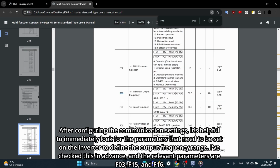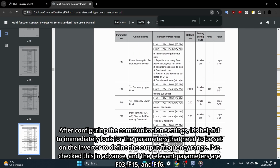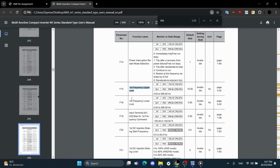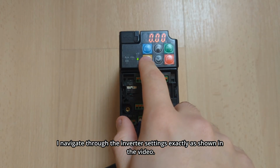After configuring the communication settings, it's helpful to immediately look for the parameters that need to be set on the inverter to define the output frequency range. I've checked this in advance, and the relevant parameters are F03, F15, and F16. I navigate through the inverter settings exactly as shown in the video.